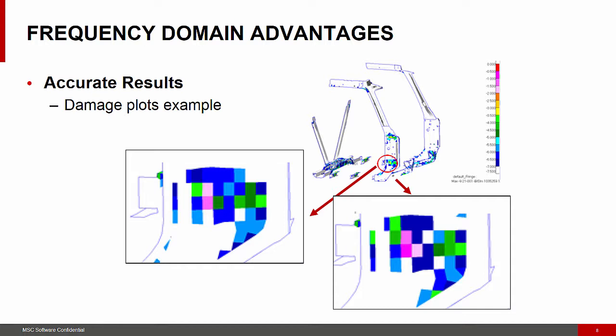The stress change needed to cause a factor of 2 difference in damage results is usually less than 10% and can be as low as 5% as well. In this view, the results are acceptable in many cases, so we can see that the frequency-based approach gives us very accurate results in comparison to the other method.